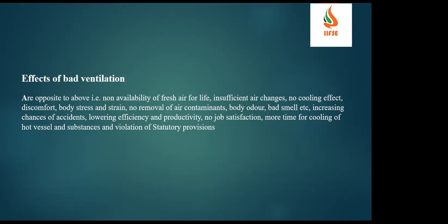So it is completely the reverse of what we have seen before. If you're not having ventilation, you will be in a dusty area, your metabolic heat will increase. So the workplace temperature will increase, and then there is no proper cooling effect. Your body gets stress because of temperature. You'll get excess sweat, so you lose water in the form of sweat, and you'll get dehydrated much faster. You'll have no job satisfaction because you're continuously working in an unconditioned workplace. All these will be the bad effects of bad ventilation.